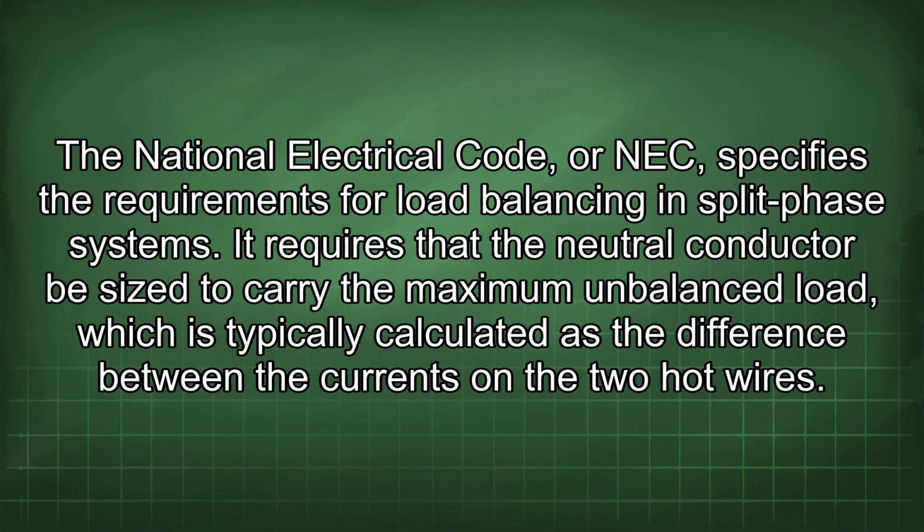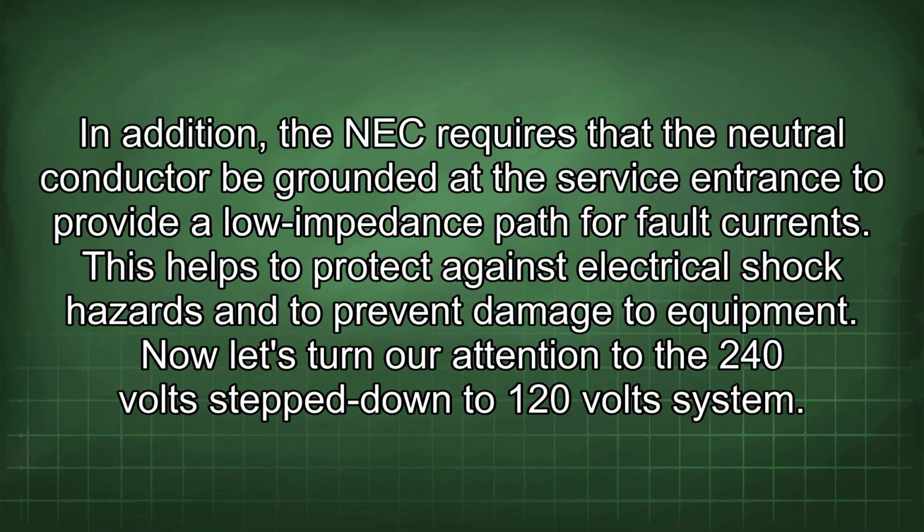The National Electrical Code, or NEC, specifies the requirements for load balancing in split-phase systems. It requires that the neutral conductor be sized to carry the maximum unbalanced load, which is typically calculated as the difference between the currents on the two hot wires. In addition, the NEC requires that the neutral conductor be grounded at the service entrance to provide a low impedance path for fault currents. This helps to protect against electrical shock hazards and to prevent damage to equipment.